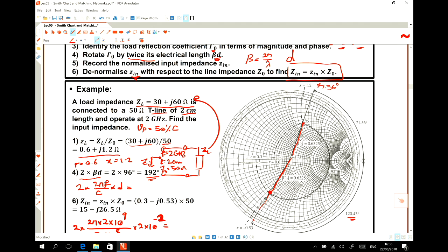How can I find which circle, for example, is 500 megahertz? Based on the value that you find for the jB. For example, jB is 159 at 500 megahertz, so this is the 159 circle. Or at, for example, 4 gigahertz, the value is 0.2, so this is the 0.2 circle. So they move from this point to this point if you change the frequency. Okay? Shall we continue?